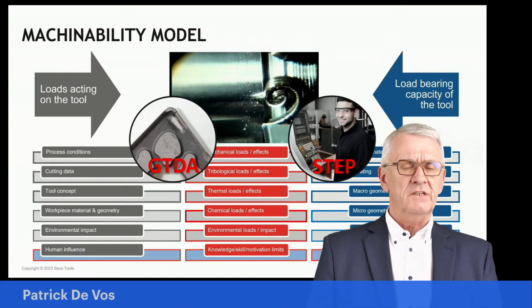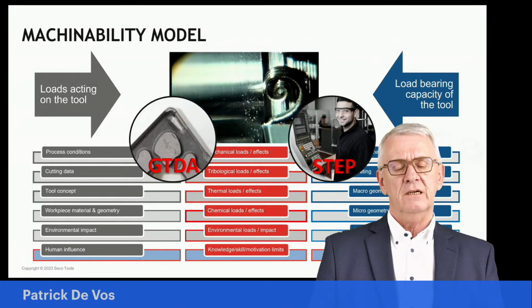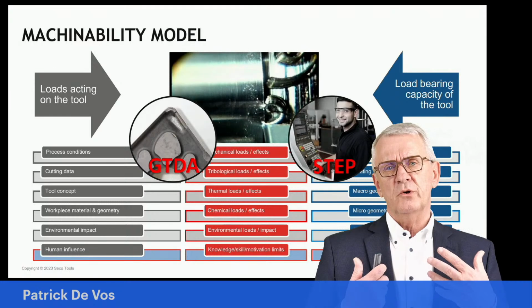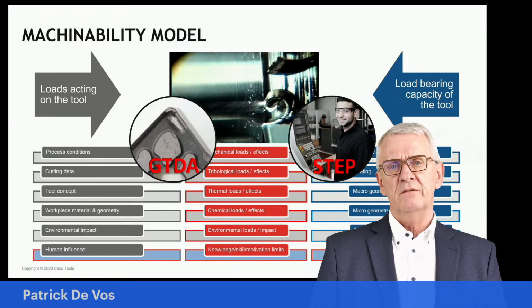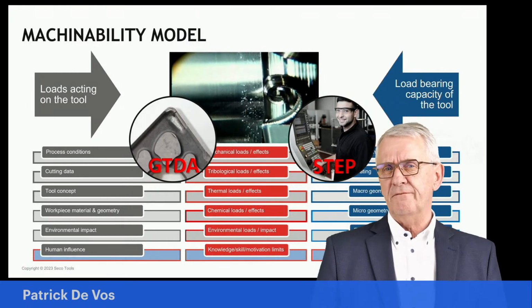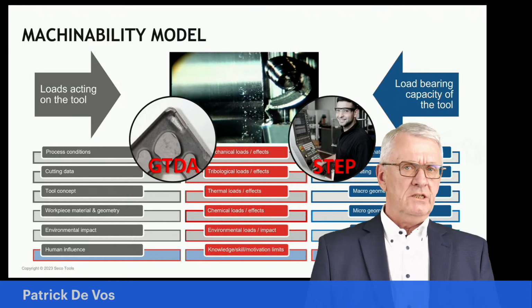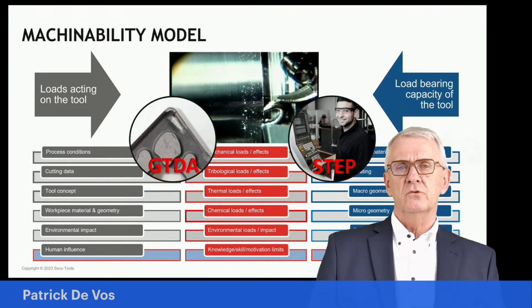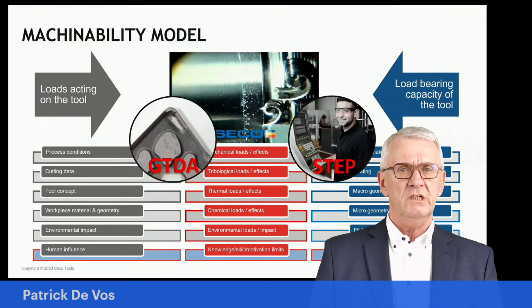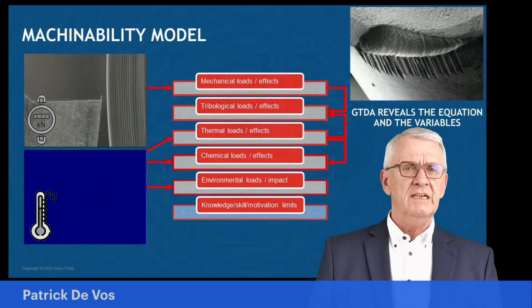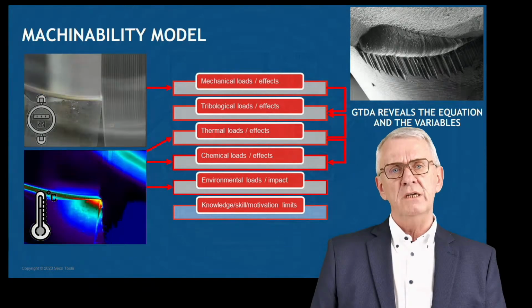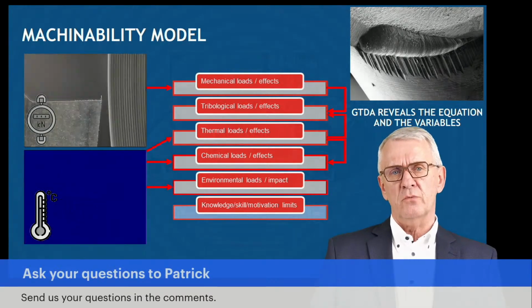Now, to know if you solve the equation in a correct way, you know my belief. I always say look upon this in a pragmatic way. Ask the people involved, people with some expertise in machining. They will tell you how they felt about the process, and have a look at the used cutting tools. Used cutting tools, if you know what to look for, tell you quite a lot about what happened during a machining process. Machining involves mechanical thinking, and that is what most of us are rather familiar with, I guess, but it's also thermal effects.